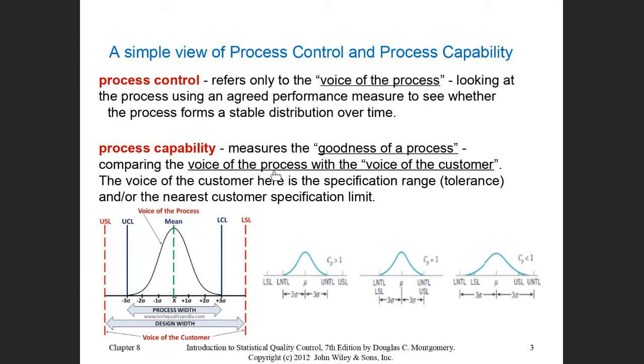Your specification for the car you would like to purchase is different from one person to another. But how is the production for a specific car, and how is the variability in that production line? This is something else. This is where we apply the control chart and make sure the variation is within control, whereas the specification is something that can be above or beyond the control limits.